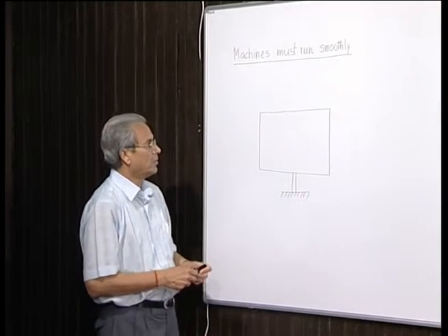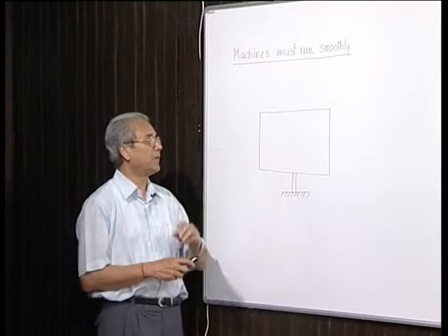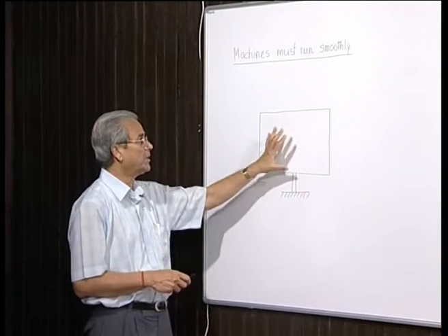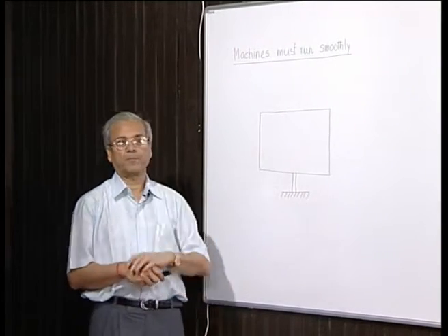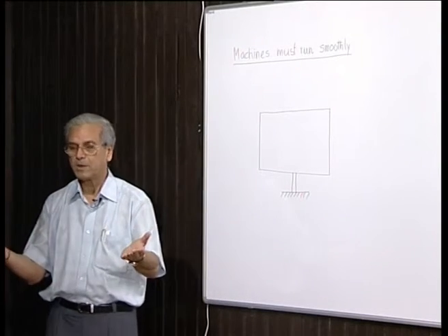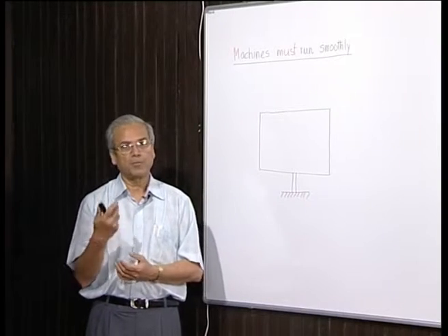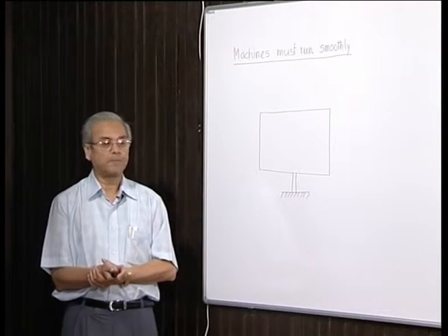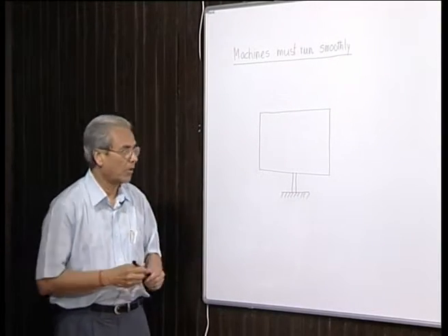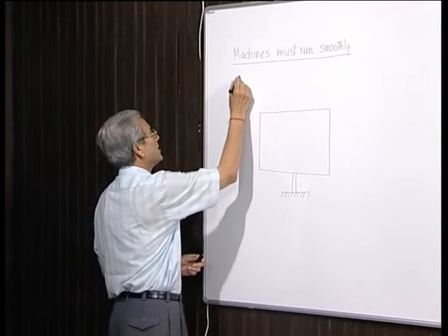Therefore, proper design should ensure that when the machine runs, the support which carries the whole system is not subjected to dynamic forces or moments. That means, in common terms, that this system should be balanced.